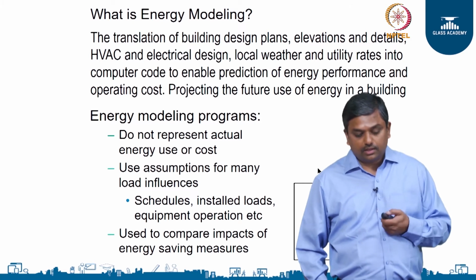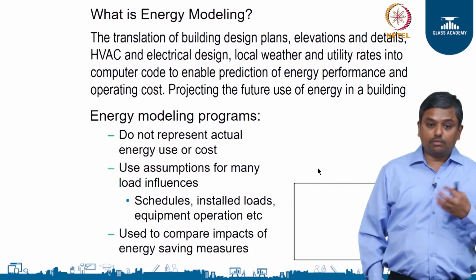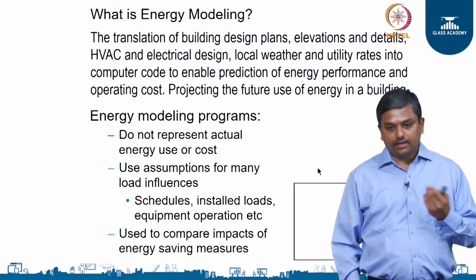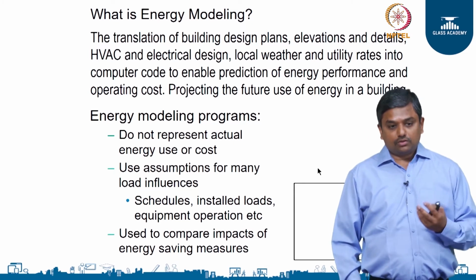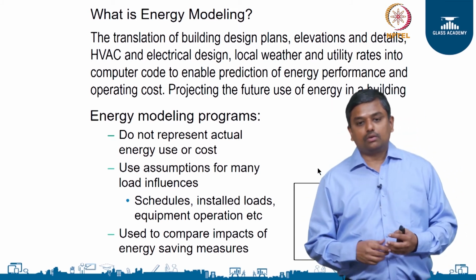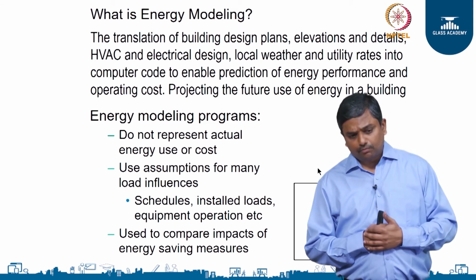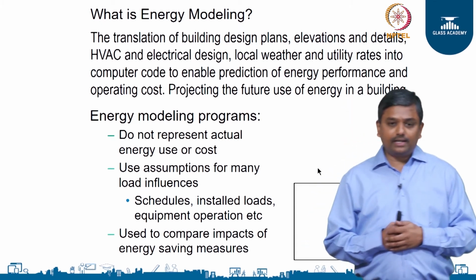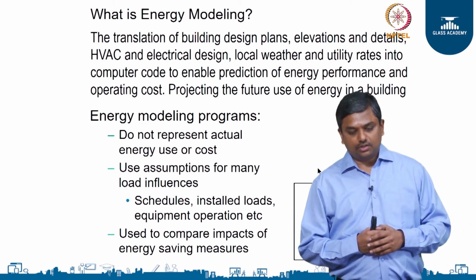That makes it very powerful, and you can play around with a lot of these parameters to find out how the building is going to behave if you change, for example, a particular glass in a particular facade, or if you add some shading devices in a particular facade, or if you want to change the operational profile of the building, the schedules of the building, the number of people inside the building. All these factors can be programmed, and you can run a lot of what-if scenarios around these parameters and arrive at very prudent design decisions, which is very important for us to make our detailed design much more effective and make the building more optimized in terms of energy performance.